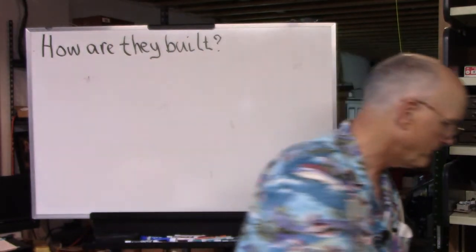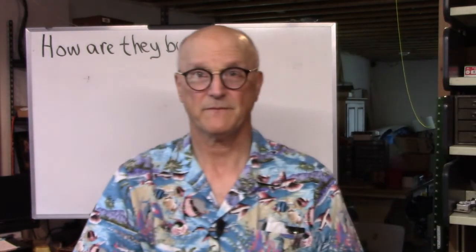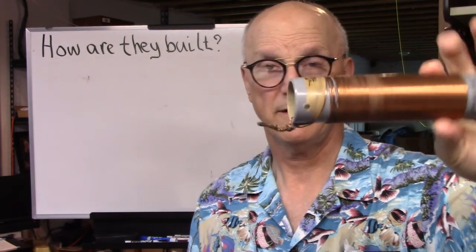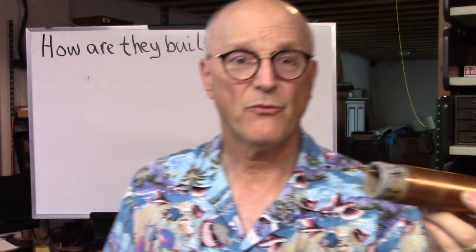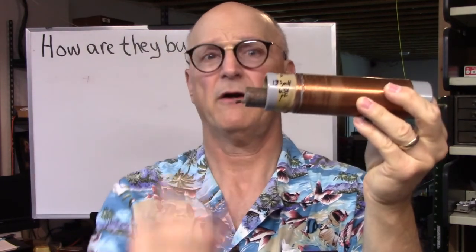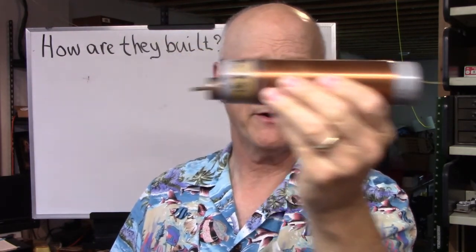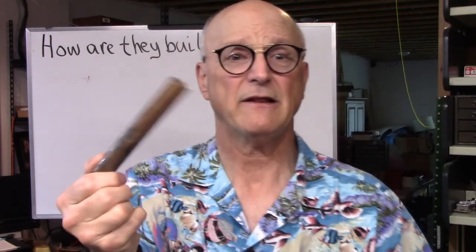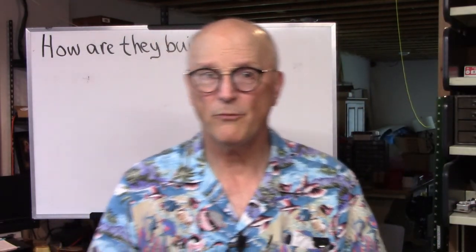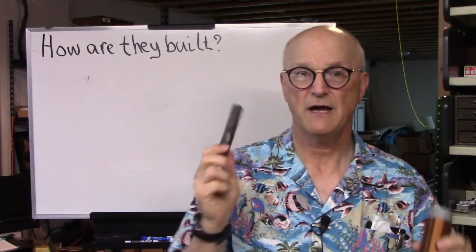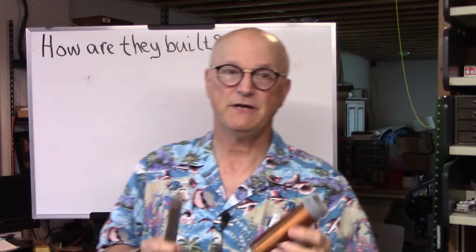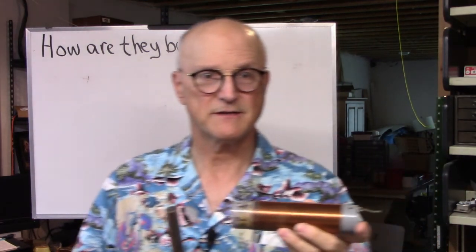Now we could take that coil of wire and wrap it around some kind of magnetically active core, such as my bar of steel here. This magnetically active material would help reduce the number of turns of wire needed to achieve a given inductance.